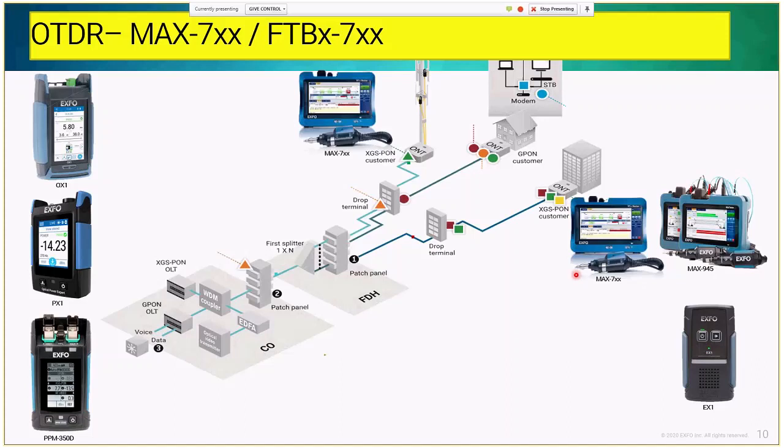Apart from the OTDR trace, you have other concepts, which is the IOLM, Intelligent Optical Link Mapper. We'll talk about it later on, but it will characterize and associate the trace to different elements using a multipulse approach, which will be much more accurate than the OTDR. And it will identify, with reduced attenuation dead zones, correctly what is the real loss of the element.